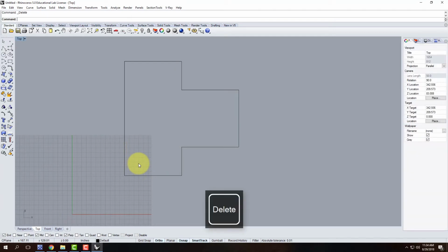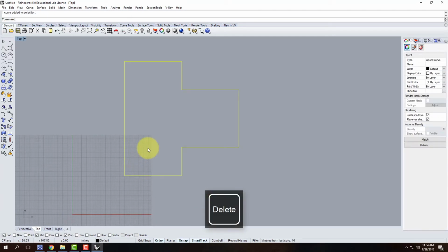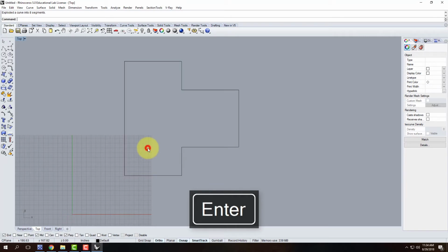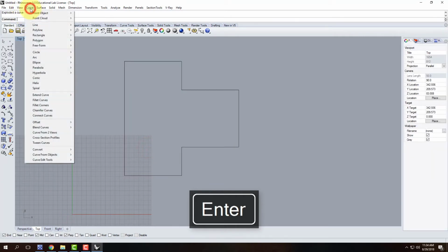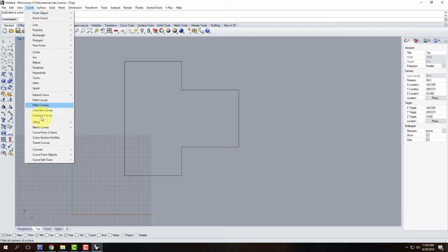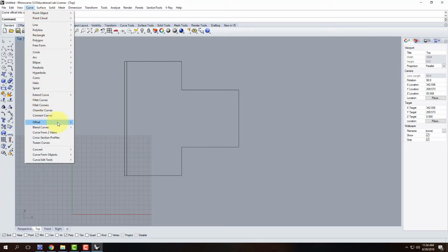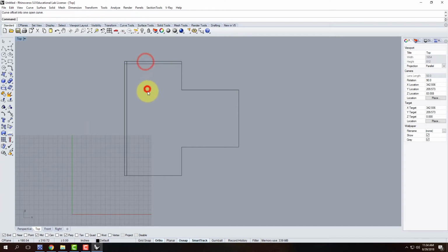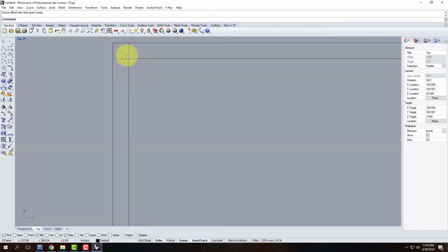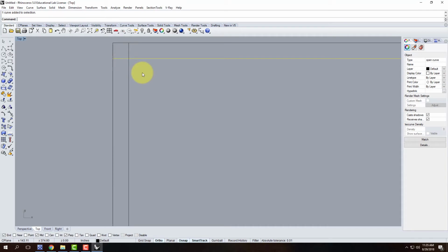6 inches from the original line inside. Now in some cases, depending on how you drew the first drawing here, you may start to do the offset. And once again, I'll go back to offset, curve, offset, offset, curve. Distance is still set to 6, and I say, OK, I want to offset this curve. Well, it didn't offset all the curves. Well, maybe I'll do it again. Curve, offset, offset, curve. OK, well, it offset that curve, but each one of these curves is separate. You can draw it that way, and it will offset each curve separately. It just creates these little crosses in the corner that you'll have to deal with later on.